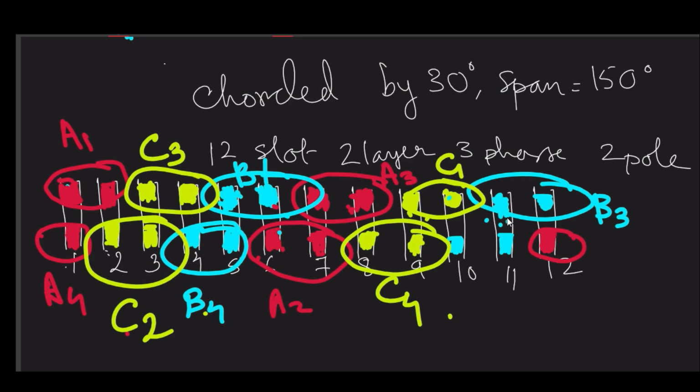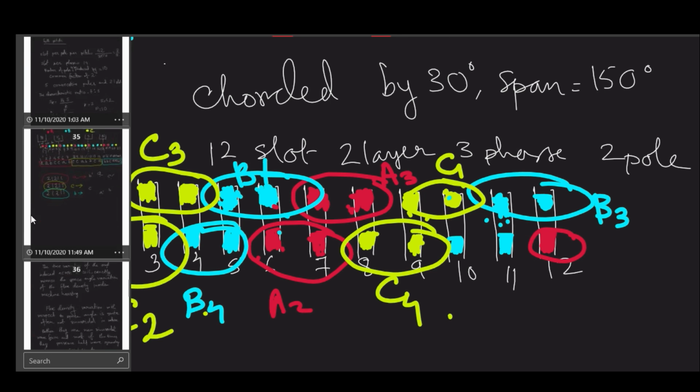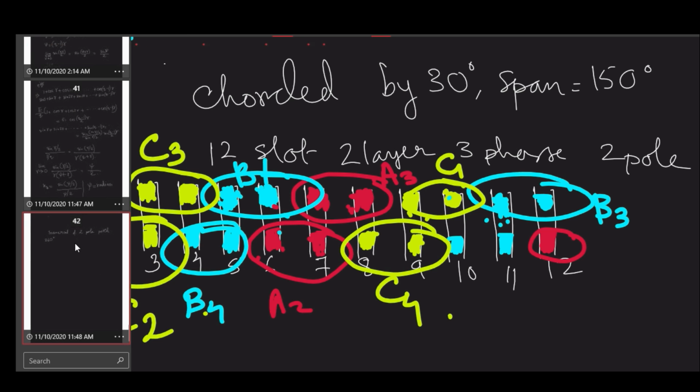Probably it was 30 degrees. Yeah, it was 30 degrees. So from 1 to 2, 30, then here 30, 30, 30, 30. So if you traverse the total two-pole pitch, like here from 1 to 12, what will you get? You will get a simple thing: by adding up those gammas, those inter-slot angles, you have already covered 360 degrees. So now let us give you a simple and easy to understand approach.